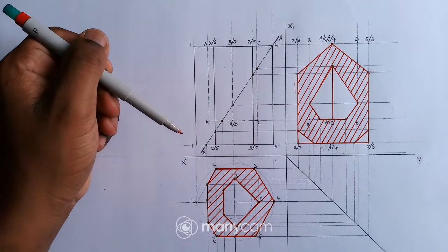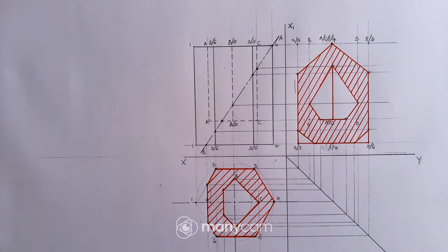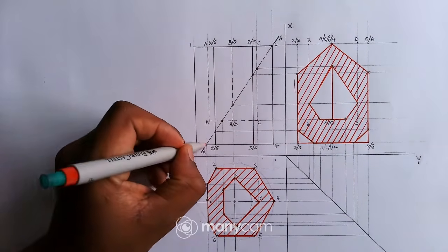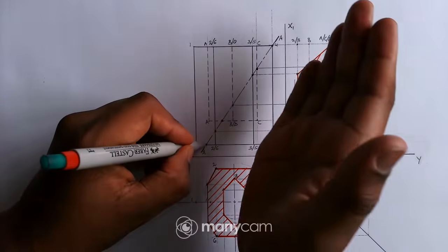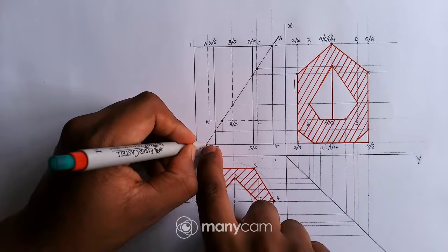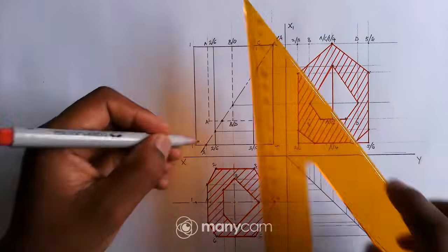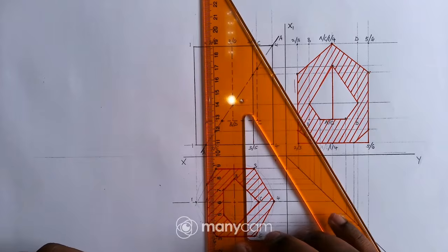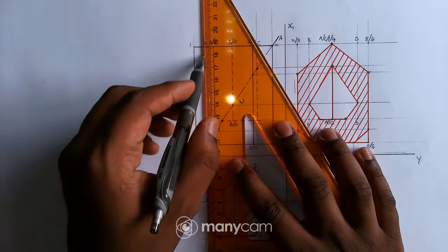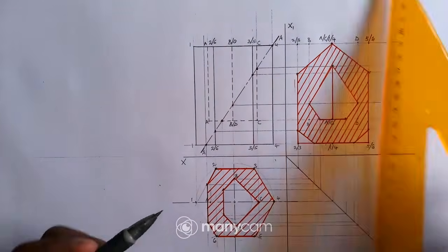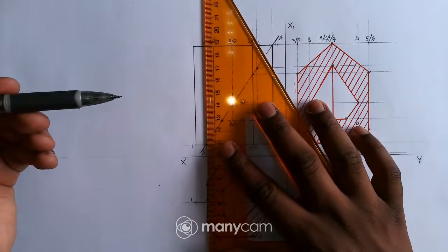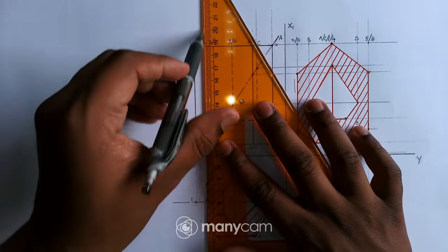So let me just show you how to tilt the cutting plane. For me to have a vertical cutting plane now, I'll use this point, right? So I'll tilt this line to be a vertical line on this point. From this point, I'll just draw a vertical line. Obviously I'll have to draw a construction line, right? So now my cutting plane will be this line. Let me just extend it up there.